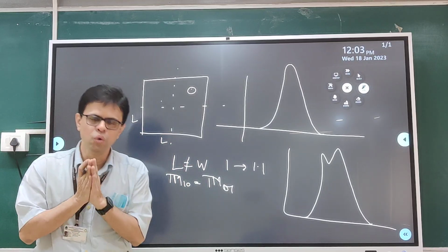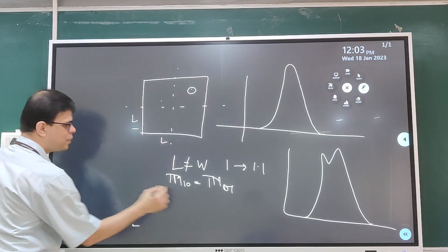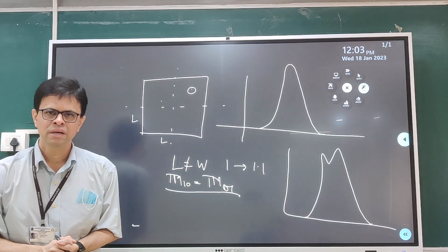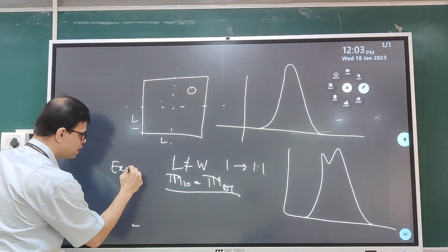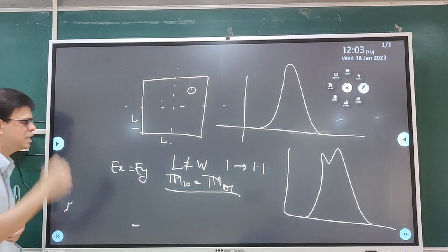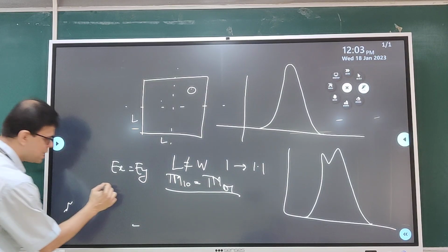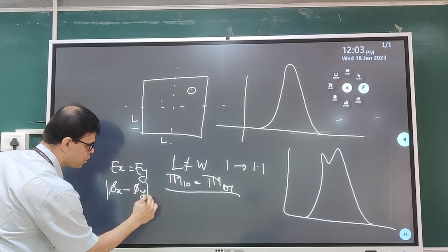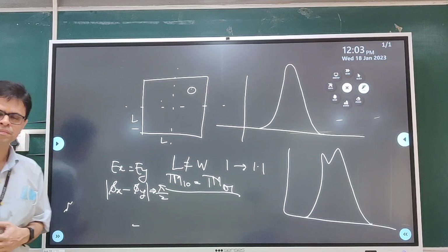Now what I want to do to realize a CP antenna, I should have optimum spacing between these two mode frequencies. That optimum spacing will ensure that Ex is equal to Ey over a certain range of frequencies, plus it will ensure the phase difference of these two is within pi by 2 radians.